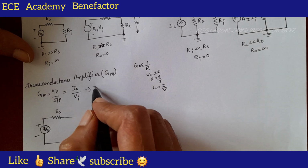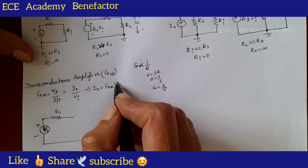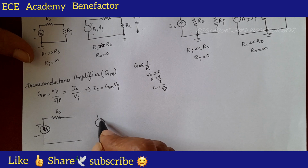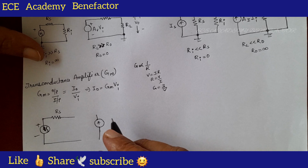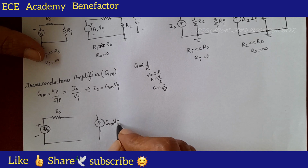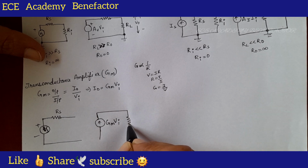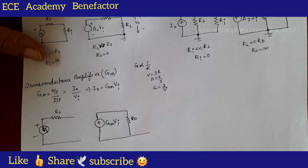What should be the I naught equation? I naught is equal to Gm times Vi. So, we need to place a current generator here. What is its value? Its value is Gm Vi. As there is a current generator, we need to place a resistor R0. So, this is the output circuit.